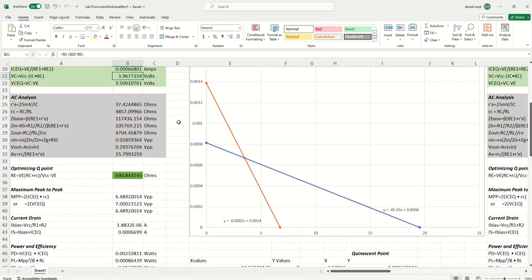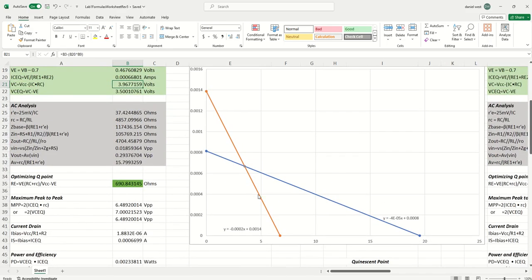And so if I look at the AC and DC load lines, so AC load line here, DC load line is there, and this is my quiescent point. And if I drag it all the way down, this is about 4, which is our 4 volts for VC. And then this point, if we drag it to the left, that's about 0.00065, I would assume, if I didn't know that it was actually 668 microamps.